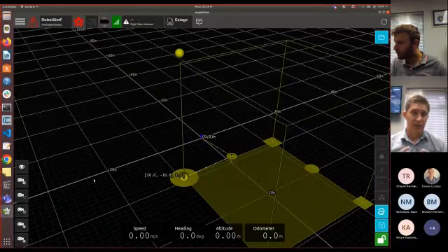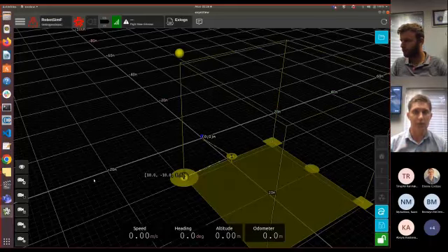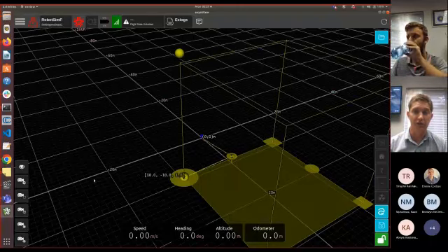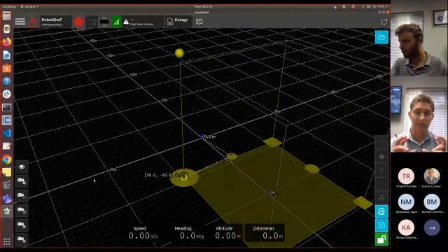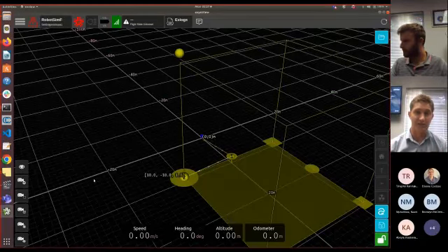So this is a solution, right? The drone and the LiDAR sensor need to be kept together at all times. It's not advisable to remove the payload from the drone, so ultimately you have to keep the system as it is. It's very important for the calibration parameters associated with the LiDAR and the offsets on the actual drone. So it's preferred and highly advisable to keep the system as it is.